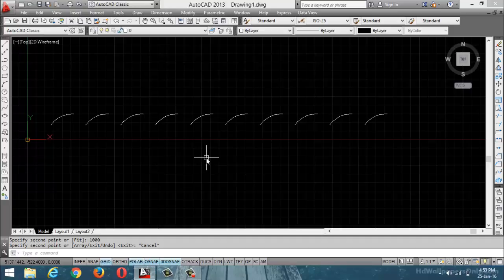Again, this is one page, the first drawing page. I have one more page, one more designing page. Now I am going to copy an object from the first page to the second designing page. Later I will explain that one also. Just write: select objects to be copied, enter. Select base point, the base copying point. Next, select the new point, the new copying location. Specify the new location. Okay, that is about the general procedure.